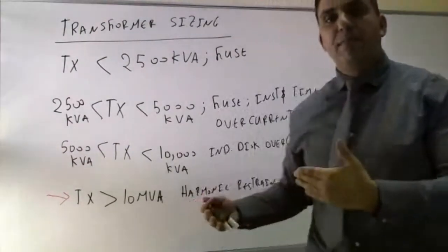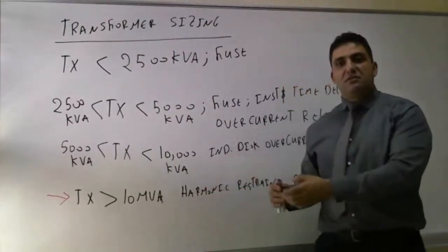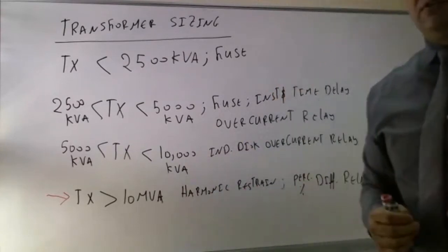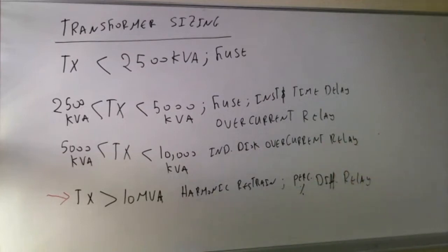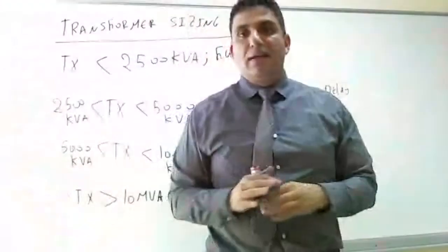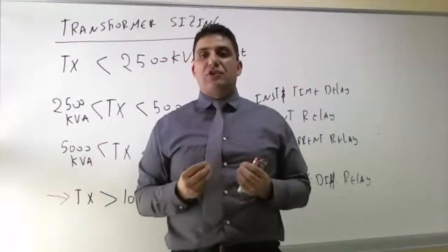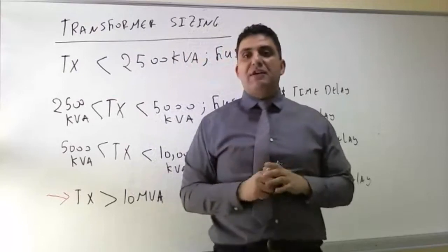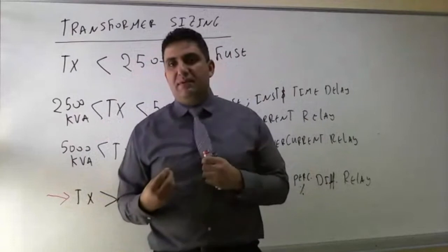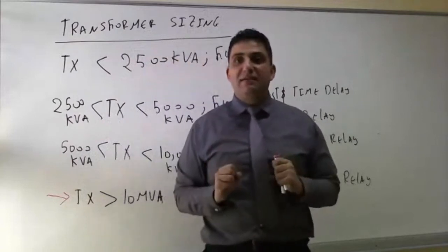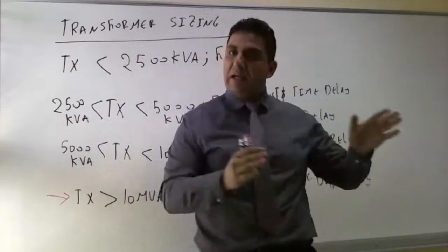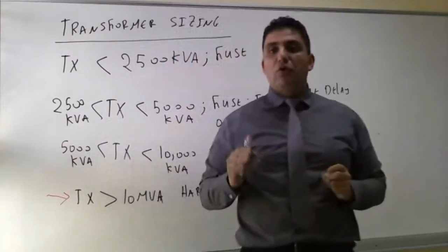Also, the transformer will have heating protections, and if it's oil-filled, there are plenty of other protection relays or protection concepts. So the third element will be the voltage level. If we have an 11 kilovolt transformer, or we have a 500 kilovolt transformer, a 500 kilovolt transformer costs a lot of money. That's why we have to use a sophisticated protection system to reduce and, if possible, eliminate the fault or the damage to the transformer.